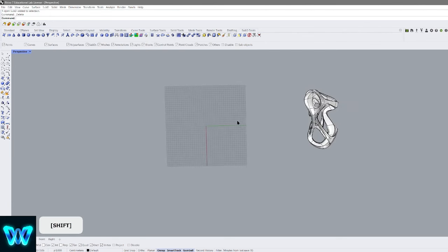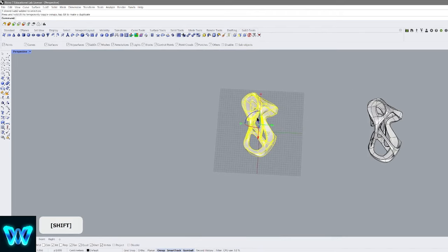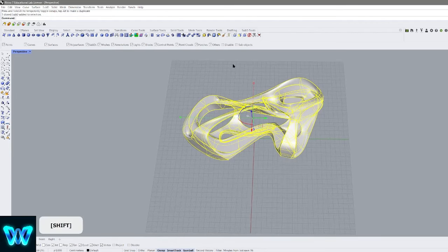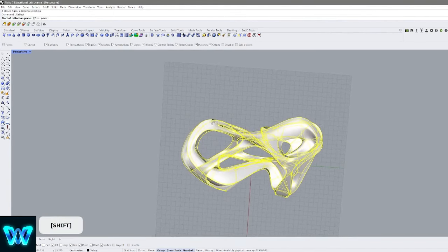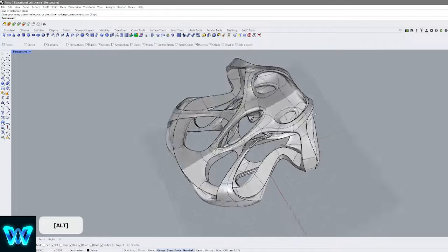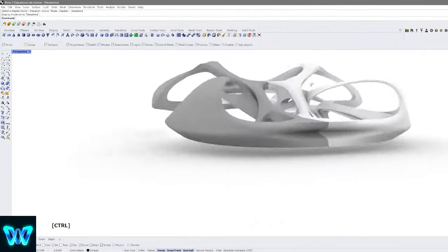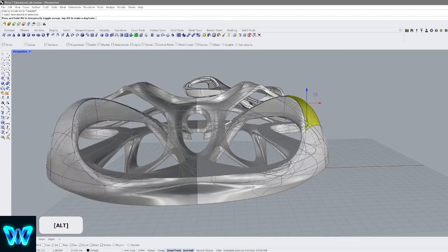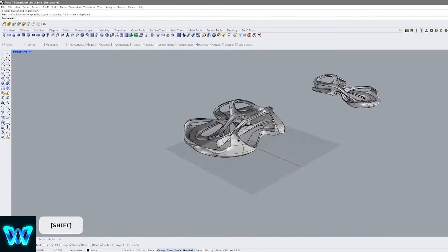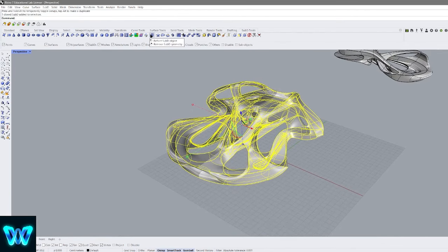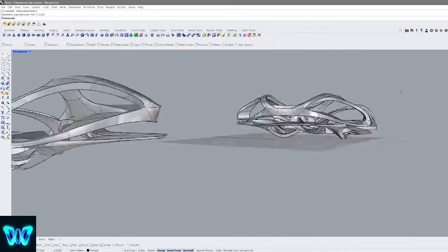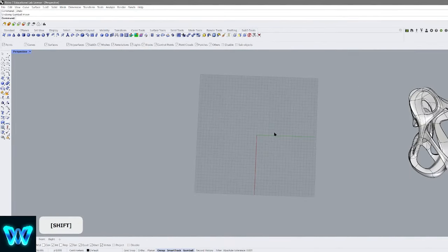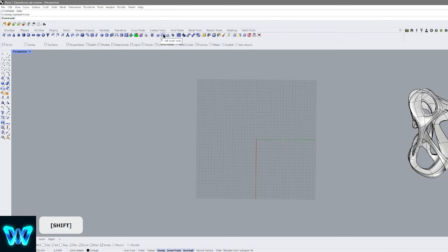Here we have reflect SubD. This one's very interesting because let's use this one as an example. Sometimes you want to create symmetry and you don't need to work on both sides, right? So all you have to do is select your shape, find that axis point that you're trying to use, and then just create that symmetry. In this case, you get something really cool. Looks kind of like a plane. And the moment you start editing things on one side, they will animate the other side. Now, in order to take it out, all you have to do is select the SubD and then right click to remove the symmetry. And now there's no more symmetry, and you can start working on just one side.